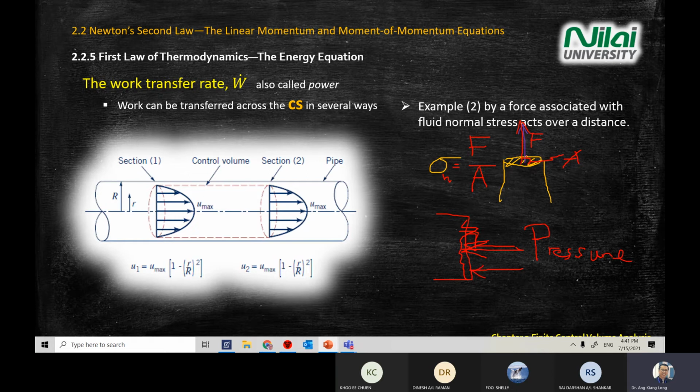So if you compare the two diagrams that I drew, the magnitude will be the same. It means you can convert pressure to forces and area. F divided by A is pressure. Only the direction is different. The way they act is different. So this means that you can convert pressure into stress. This is stress. If you take F divided by area, you get stress. Normal stress, especially. Why normal stress? It is just to strengthen the description that the force is 90 degrees to the area.